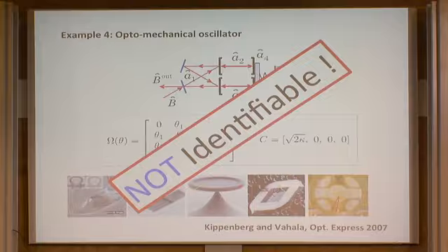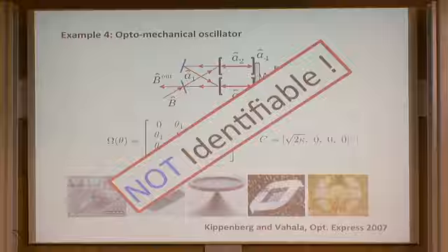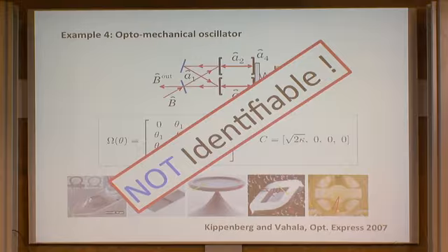Even if you don't have the right parameters, you can still design the right control system. The same if you just want to simulate the system. If you want to simulate the input-output behavior, it doesn't matter what's going on inside. So it wouldn't matter if it was not identifiable. It's only if you want to work out what's happening inside that you need identifiability.